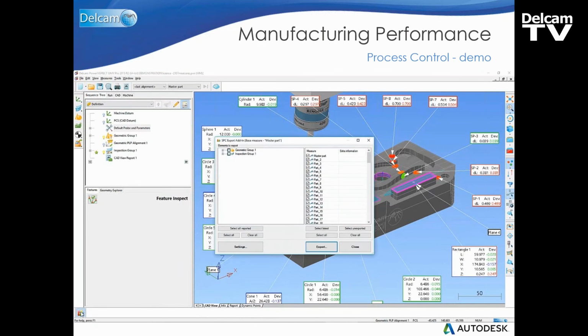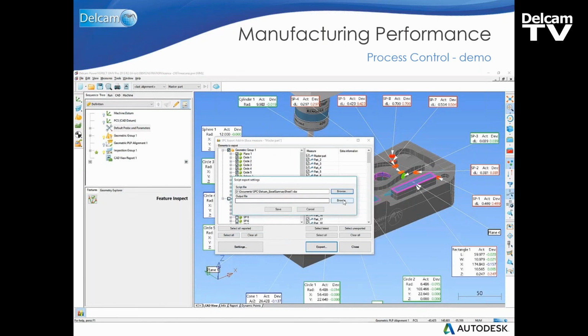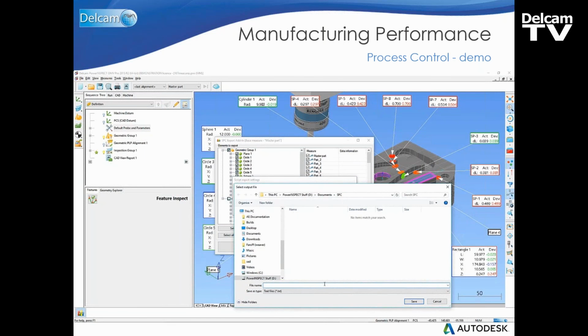and then what we can do here is that on the left-hand side of this dialog, we've got our different inspection groups. You've got a geometric group and a surface inspection group. And on the right-hand side, we've got all the parts in our batch. So you can see there part number 2, 3, 4, 5, 6, etc. And these are new measures in PowerInspect. So from the left-hand side, we select the critical reference features we're interested in. We don't necessarily need to select every feature to monitor the process consistency.